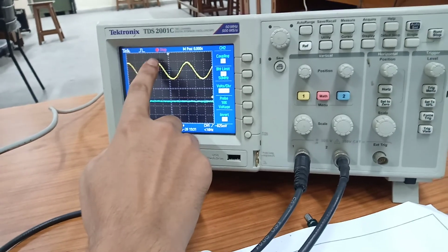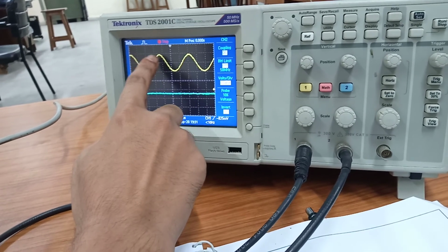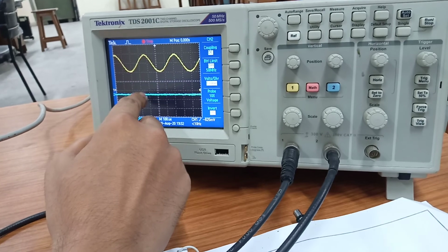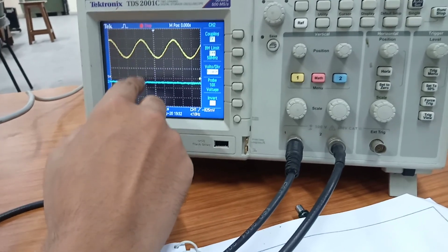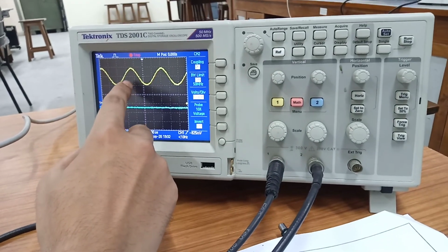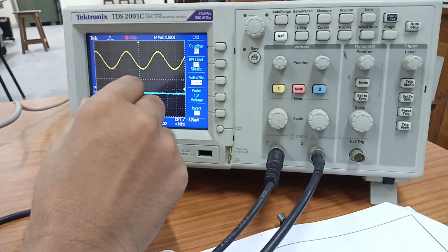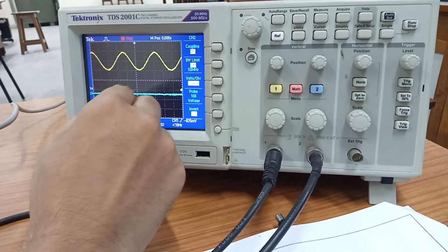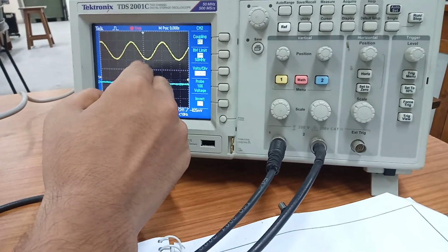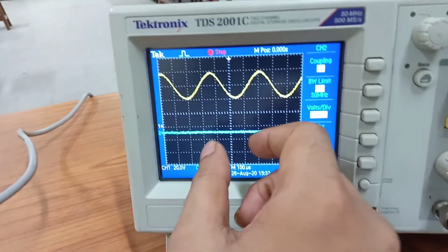You can see there is a crest and trough where the amplitude is maximum. As per the frequency modulation technique, the frequency will be maximum here. So after modulation, the modulated wave will have maximum frequency here. It means the waveforms will be closely spaced here, where the amplitude is maximum, and where the amplitude is minimum, there will be a space between the waves.